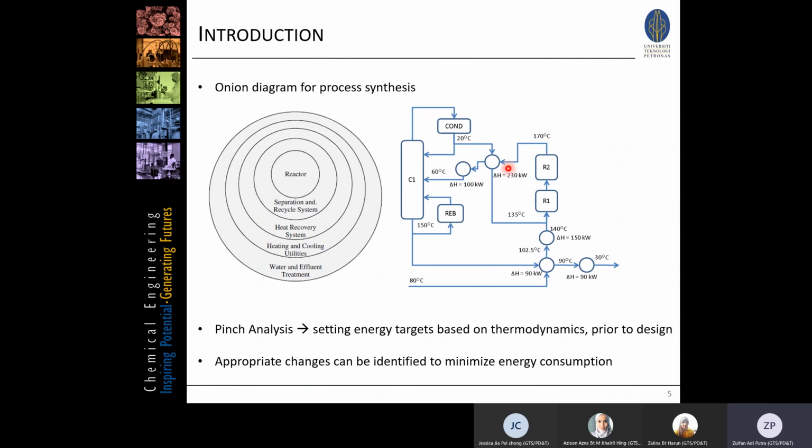So basically we have 1, 2, 3, 4, 5 exchangers that we can do something about. We have the stream data. I think you know already by now that we need to have the stream flow rate, and then the temperature data around the exchanger, and we also need the duty. If we know the MCP of the streams, then we can calculate the duty accordingly. If we don't know the MCP but we know the duty, then we can also calculate MCP accordingly. We need to know the temperature. That's the number 1 rule. So that's the typical data extraction that we take from the plant.